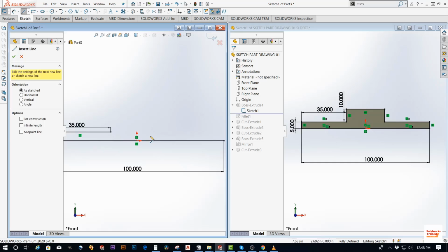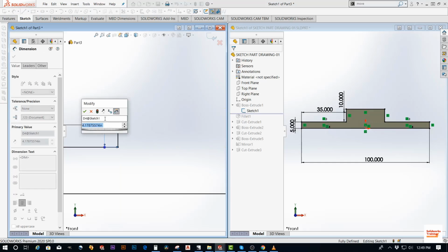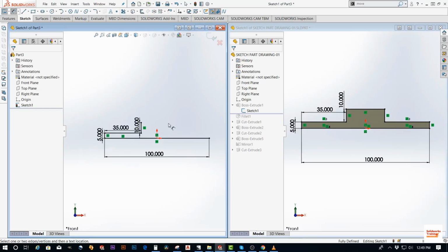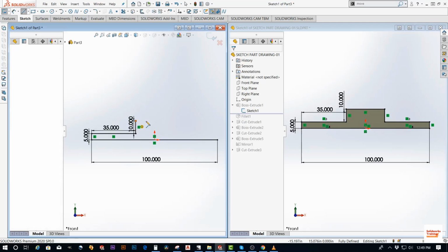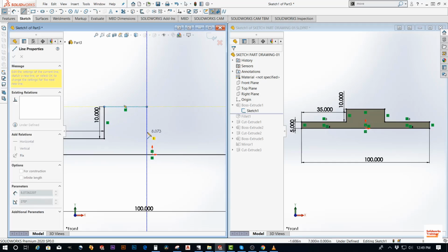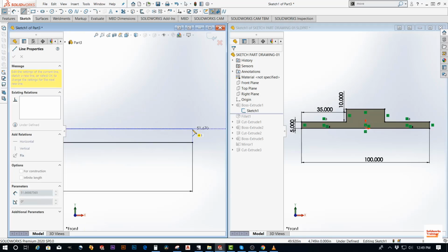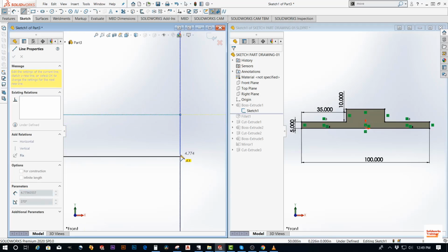And we'll do the next line, which is 10 inches vertically, and we'll do the rest of the line. Again, if we hover it horizontally aligned to this point, it will create a blue dash line, and it's called object tracking. So just follow the object tracking.